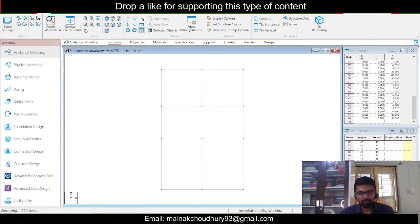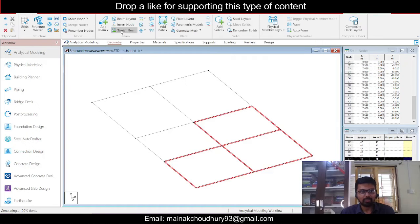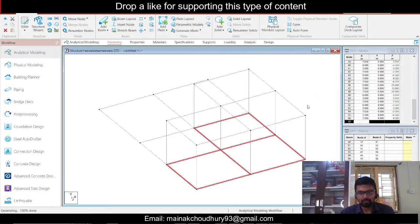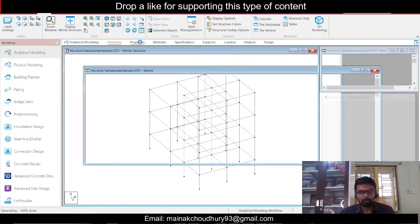We'll see in the plan which portion has the open terrace. This portion and the staircase portion have the plan. Select this first, press control and then select this. So these areas are selected, and then we'll go to the isometric view, again geometry, then translation repeat, y direction, 3 meters, single step. Click on link steps and then click on OK. So this is done, and you can see the whole structure here, and then you can go to the properties.